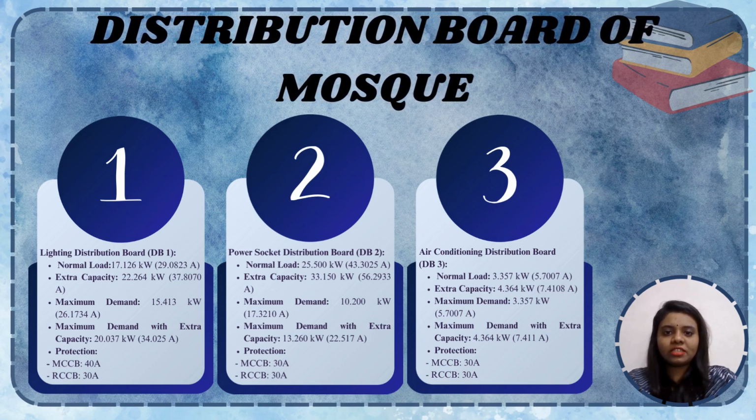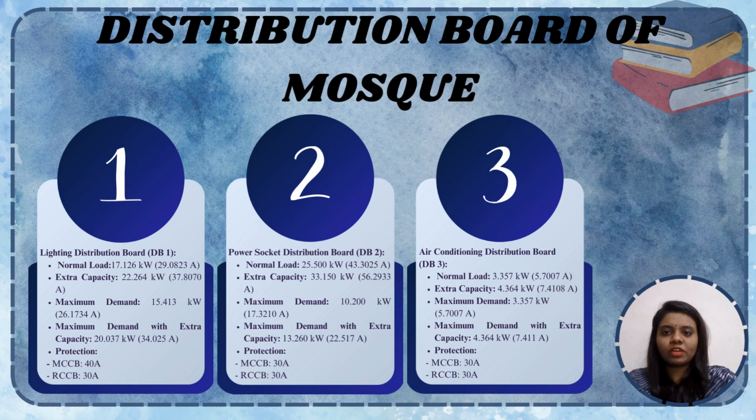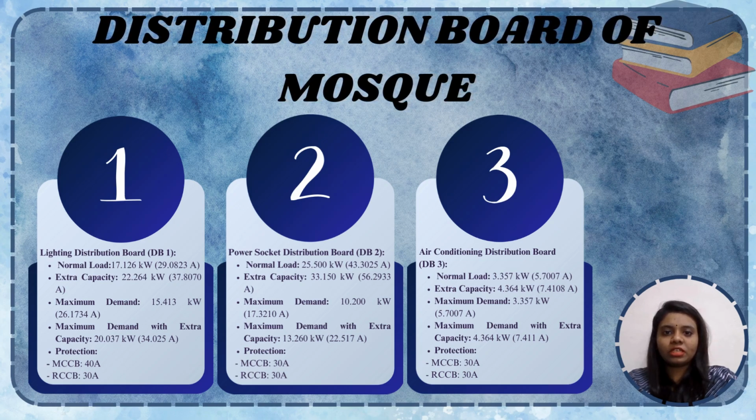The MOSC electrical system included three main distribution boards for lighting, power socket, and air conditioner, each with a specific load and protection. First of all is the lighting DB. The initial load capacity is 17.126 kilowatt, 29.0823 ampere, with the extra 30% capacity added for consistency totaling 22.264 kilowatt and 37.0870 ampere. The maximum demand is 15.413 kilowatt and